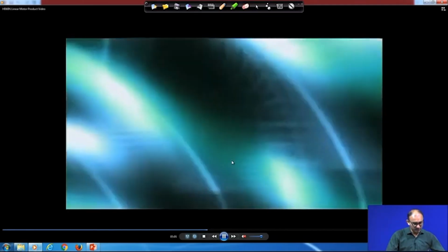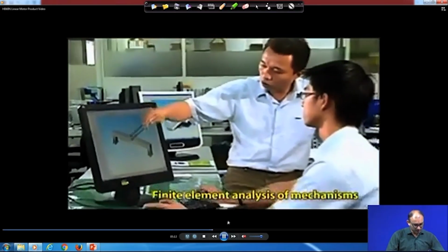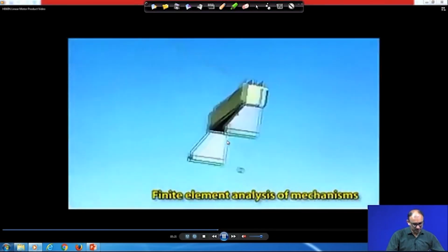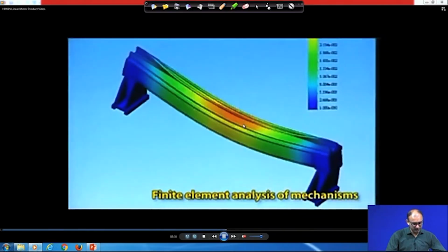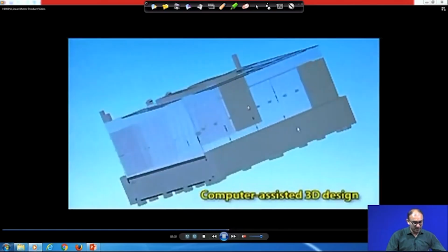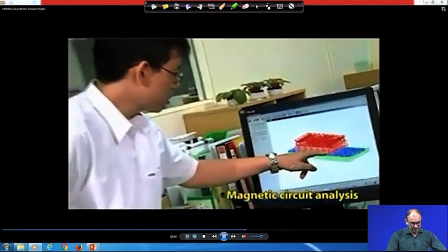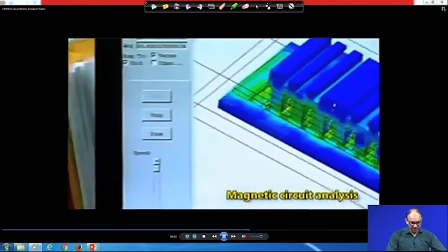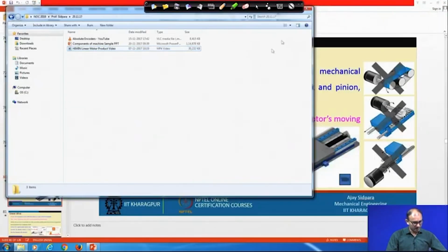And then when you build this system, you have to supply the current, and finalize the straightness, the losses of current under operation, and the heating of the system. All these things you can think of through this analysis, called finite element analysis. You can also do some frequency mode analysis, to see how much bending of the rail there is when it is under motion. If you are supplying current, what is the heating of the whole component, and where is the heat concentrated? Those things can be analyzed by these software. So, this is all about the magnetic circuit. Let us not discuss this more right now, because these are used for simulation and design analysis only. So, this is all about the linear motor.